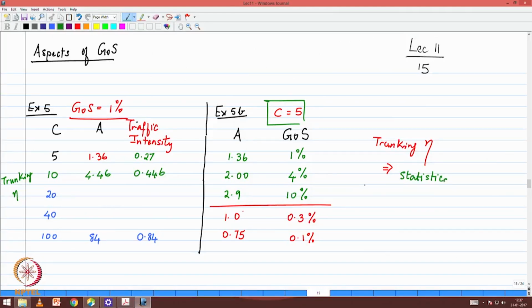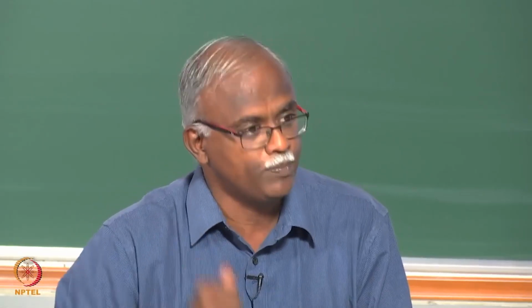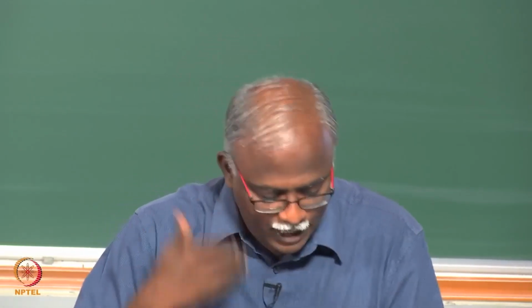This is leveraging what we know as statistical multiplexing. Any questions? Hopefully this gives you a very good handle on understanding why we said don't do too much sectorization, or try to make your cluster size as small as possible, so that you can get as many channels in each cell as possible. So that's the thinking behind it.